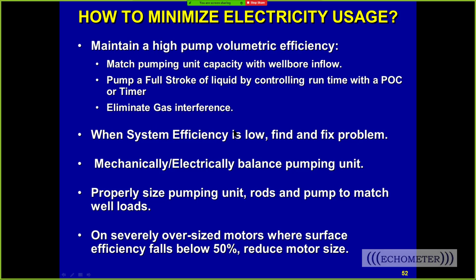When the system efficiency is low, find what's wrong and fix it. If you're out of balance, balance the pump unit. Now, not only balance the pump unit, but you ought to maintain the pump unit. Probably every year or every 6 months, the unit ought to be maintained and cared for and serviced to keep it in top-notch operating condition.